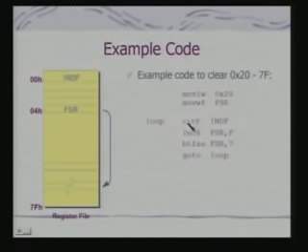So, we are accessing the register INDF, and as we access INDF, we are actually clearing the location pointed to by FSR. The initial location FSR was pointing to 20. So, that location will get cleared, and then you increment FSR and go through that loop.